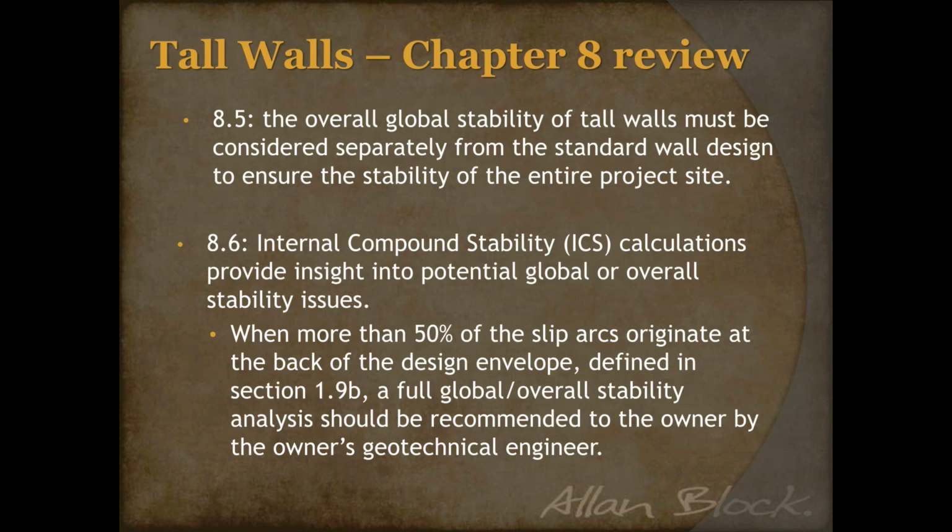Otherwise, if you are the geotech or the site civil on the project, you might go beyond that. However, with the tall wall, it is a separate calculation. You can't just consider it all in one. You do have to consider if global stability is going to be a concern. And how do you determine that? In some cases, internal compound stability.